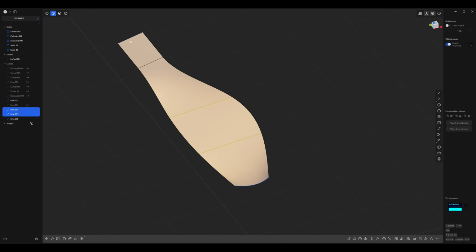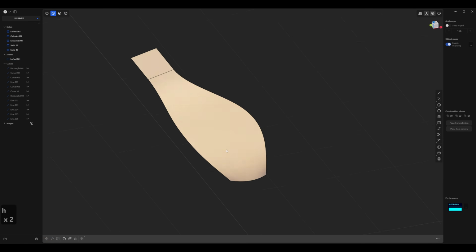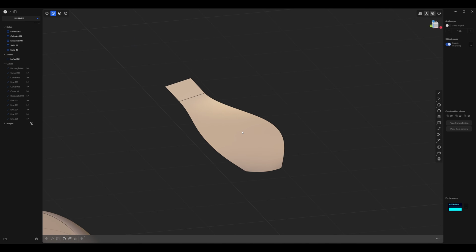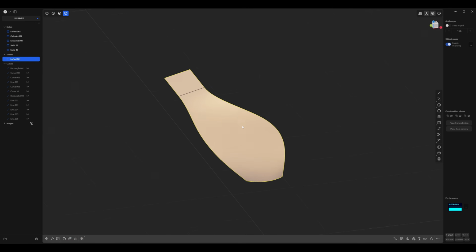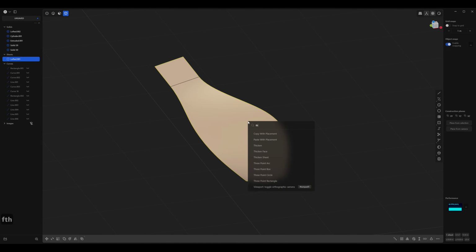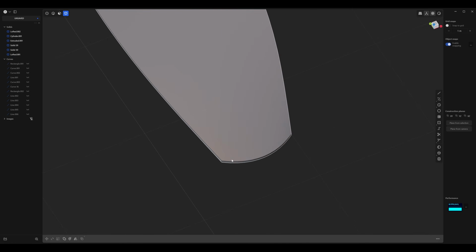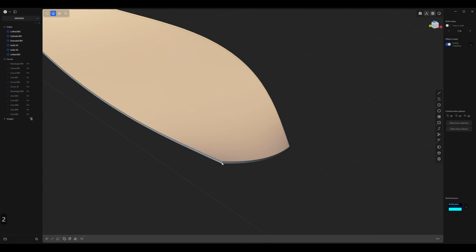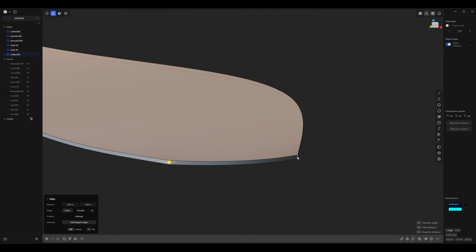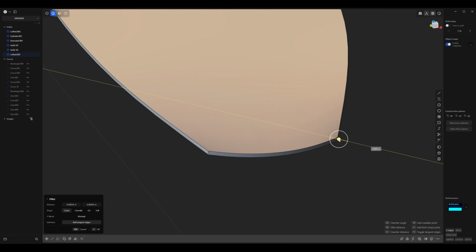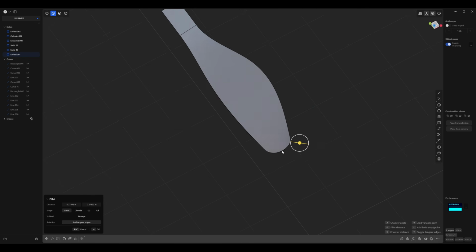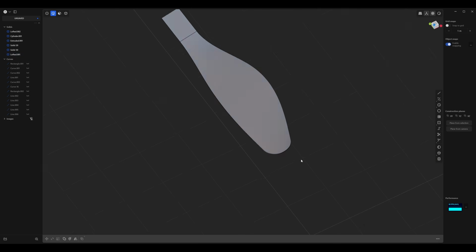But before that, let's just go ahead and select these curves and hide them. So press 4, go to body mode and select it, and then press F and search for thicken. And go ahead and drag this handle out a little bit. And right click. And I do want to soften this transition, so I'm going to go to edge mode by pressing 2 and shift selecting both edges, and then just giving it a bit of a fillet here. Maybe something like this.